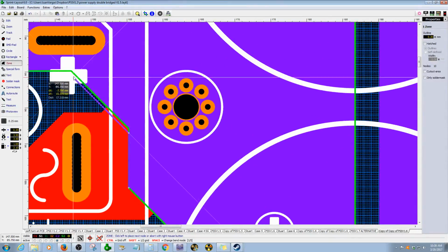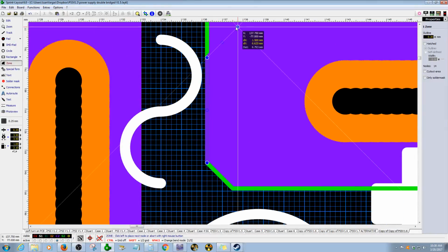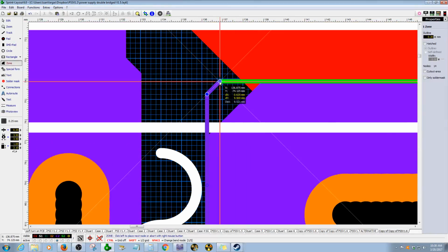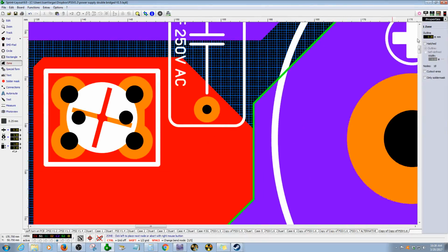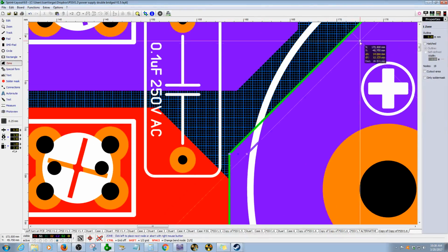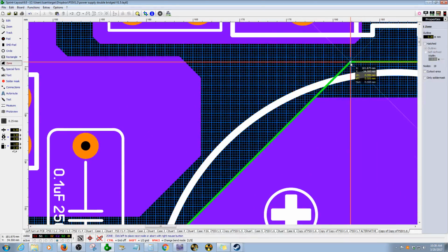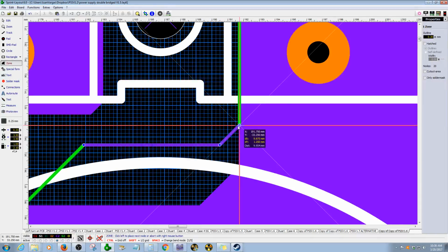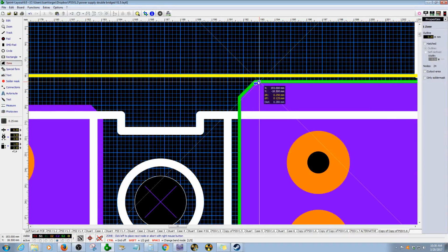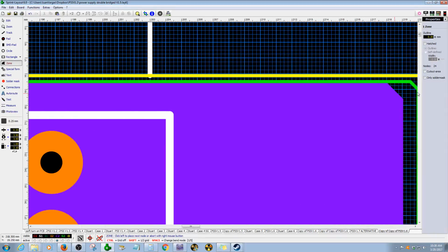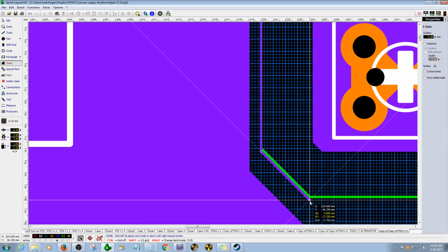The setting that I'm using is 45 degree. So every time I trace the line, it will also automatically create a 45 angle trace. Basically, it's going to follow that design. If I press the space bar, it's going to have different settings of tracing, routing. That's okay, I can fix that later. Routing the copper area zone of this design.